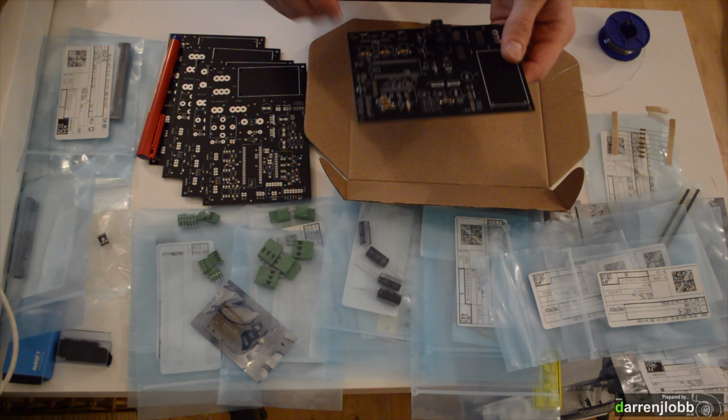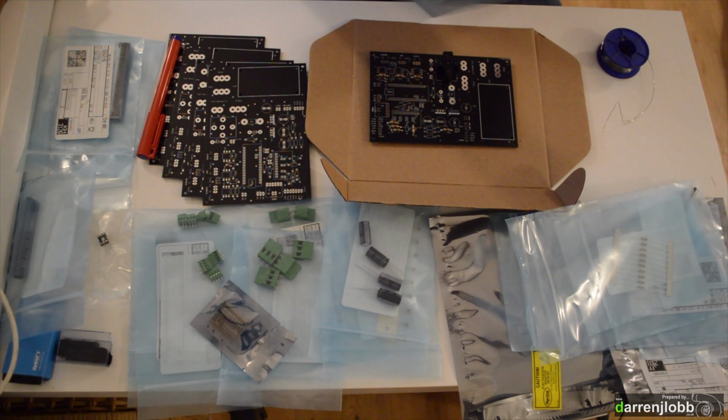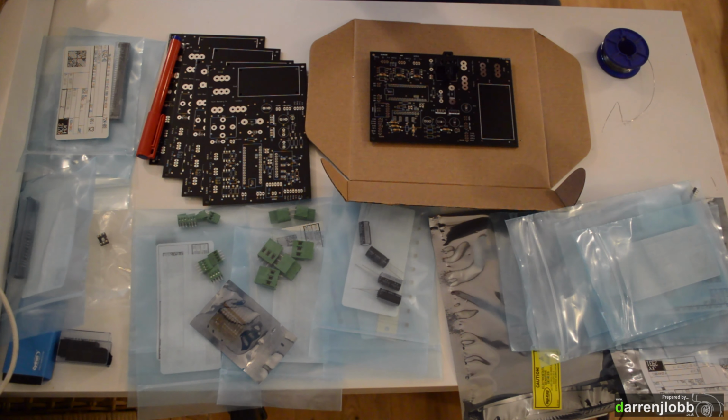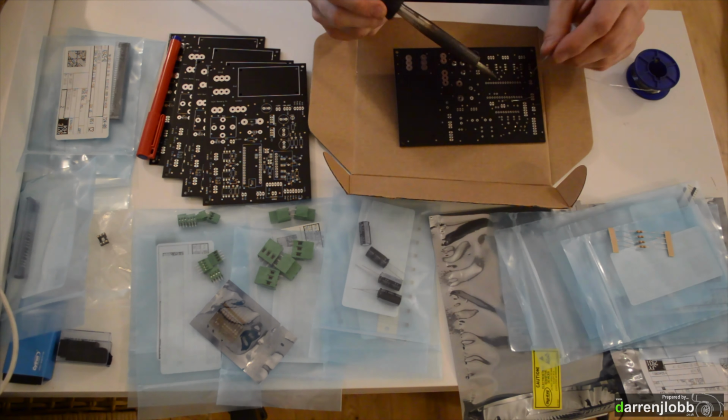Right, that's all the 1K resistors done. I just picked a component and then did all of that component. So now I'm going to move on to the 330 ohm resistors. Again, these are all labelled on the text document, so you haven't got to worry. Exactly the same really. Resistor 1, which is 330 ohm, or R1 on the PCB.